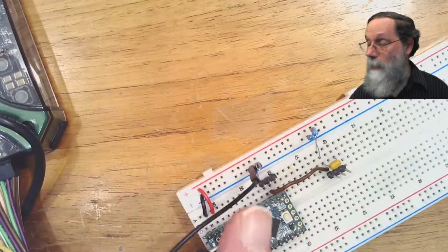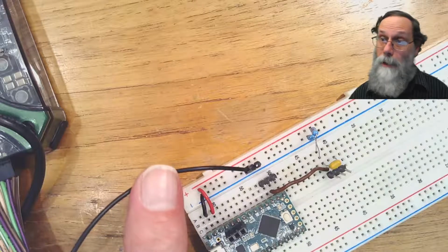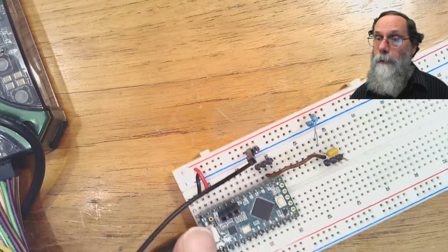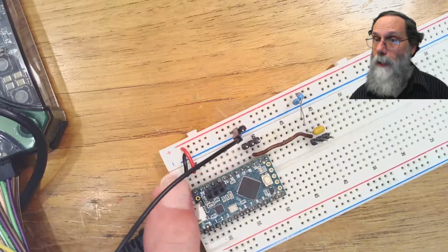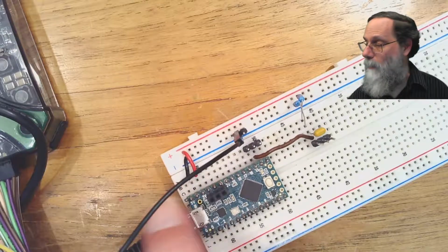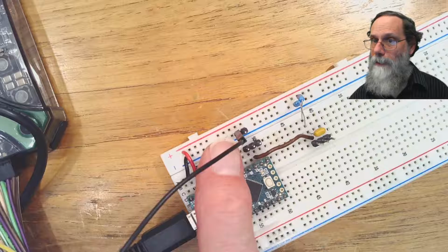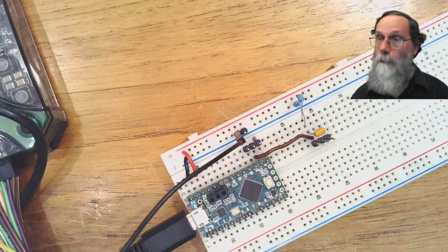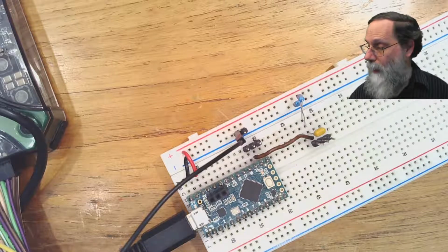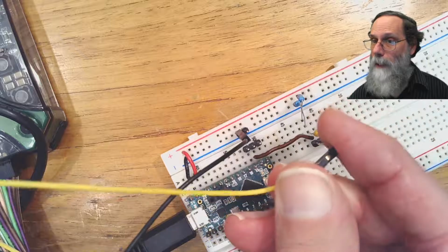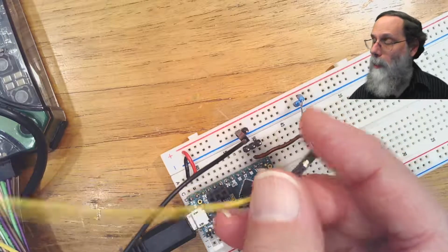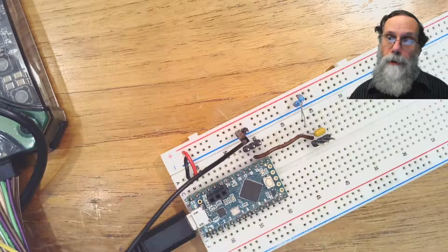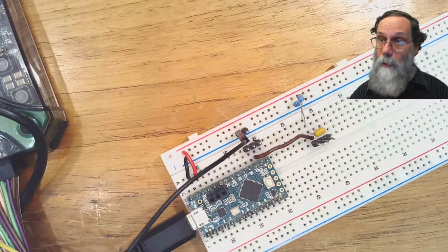Okay, so the function generator has two wires coming out of it. One is a ground wire, and we'll need to hook that up to the ground here of the TeamCLC. You can see that the ground wire here is connected up by a black wire over to that long blue part there, and that's then connected to the ground from the Analog Discovery 2. The other wire, the yellow wire here, that's waveform generator 1, we will hook up eventually to the pin that's A0 on the TeamCLC so we can record what is coming out of the waveform generator.